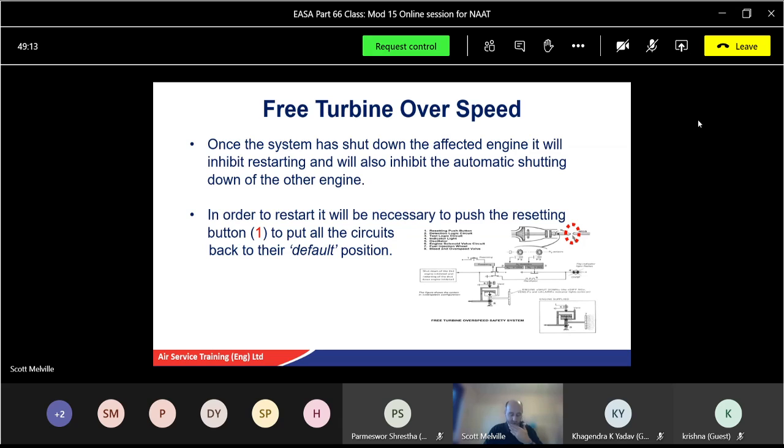Right, let's just double check on there. Any questions on that? The reduction gearing we've covered already. Got a quick run through there anyway. Might want to make a note in your books. I think it's the same in your old books anyway. Reduction gearing, as I said before, about 100 to 1 for the rotor and about 5 to 1 for the tail rotor. Again, they're just examples.